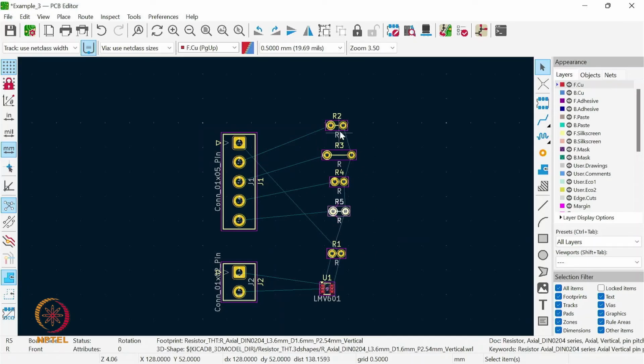You notice that these footprints are different for R2, R3, which we did purposely to show that we can use different types of components for different applications. For example, one path is low on power, so we can use a small resistance. However, one path is carrying high power, so in that case we can use a big footprint component to sustain that power.